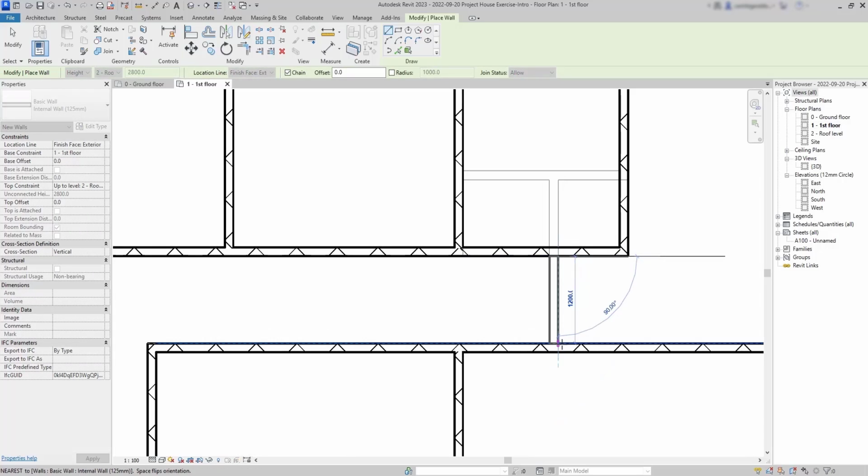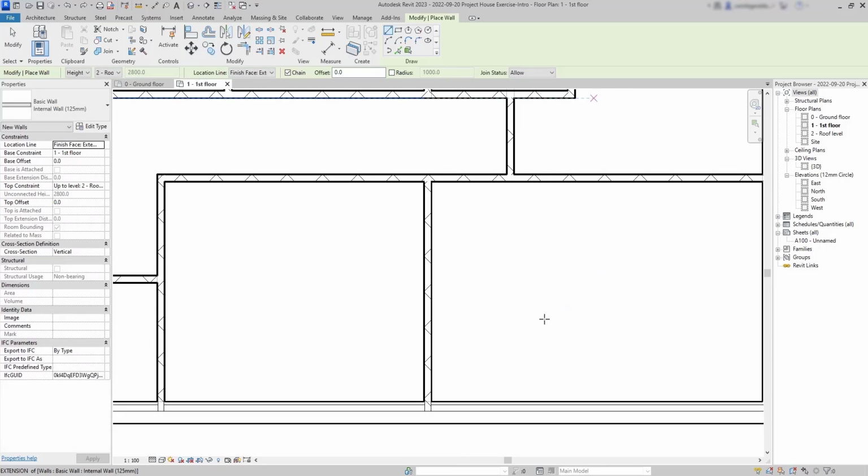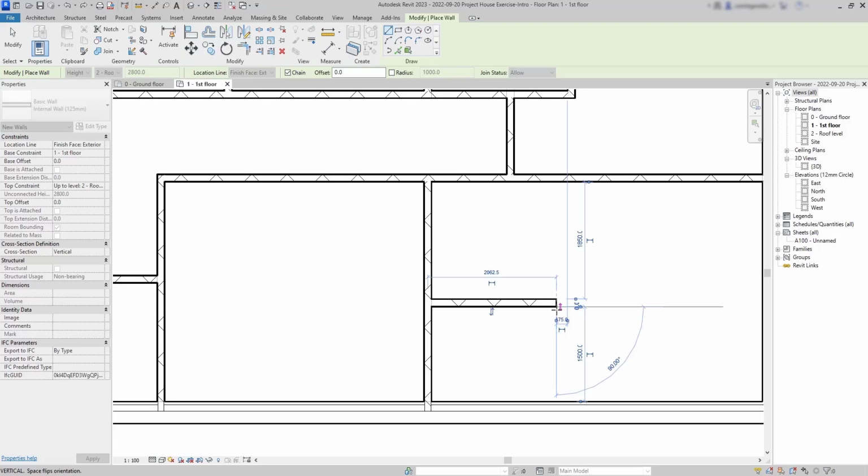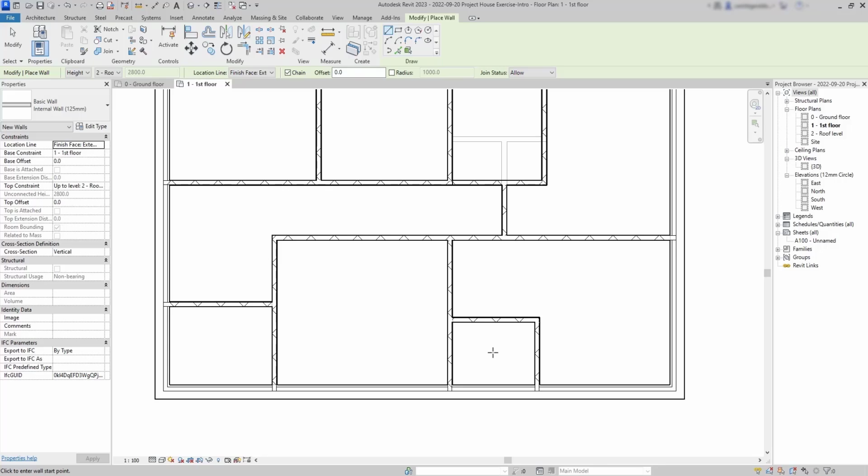Now I just need the remaining walls. And now look at this tip. Actually, to draw a wall in an exact location, it's not required to have the endpoint, as most of the time if you place the pointer at the wall, this temporary length appears, and we just need to type the value. Then this time, as this distance will be 2 meters, look that it's also easy to place the right length by only moving the pointer. So we have finished all the walls in this exercise.